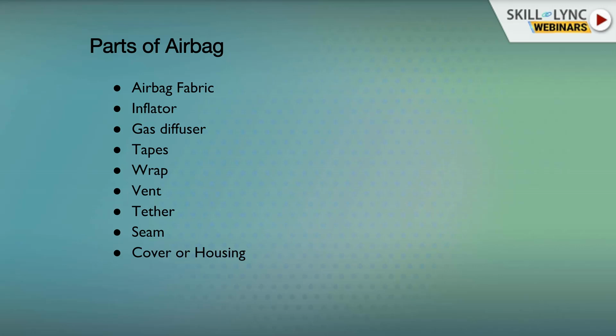And there is something called a seam. Seam is nothing but a region. These airbags have to be stitched in order, the top layer and the bottom layer have to be stitched in a certain way. When you go for stitching, there is a possibility of fabric leakage. Whenever you stitch something, whenever a thread goes inside, you are actually creating a hole. So it is also a weakness area. Around that region there will be a mass flow, considerably low, but it has to be considered when you design an airbag. That region is called the seam region.